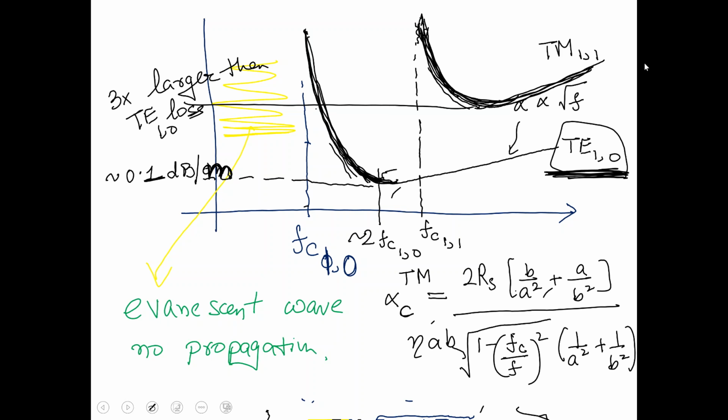But then the coaxial cable, because of the inner conductor, has loss, and I don't know whether you did transmission lines and studied the loss there or not. But the loss in the coaxial cable, because of the resistance in the coaxial cable and because of the leakage between the two conductors, starts to become very, very high as you increase the frequency. So the coaxial cable becomes very, very lossy at high frequencies, as opposed to a rectangular waveguide with air in it. So different applications, right?